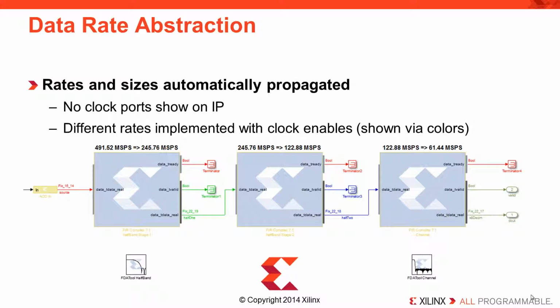System Generator for DSP is a data path design environment. Blocks representing different DSP functions, like FFTs, FIRs, and forward error correction, are placed on the Simulink canvas, along with stimulus blocks, or sources, and viewer functions, also known as sinks. The data path abstracts some signals, and since DSP is intrinsically sample-based, we abstract the clocking while automating data path growth, or dynamic range and precision, from one block to the next.